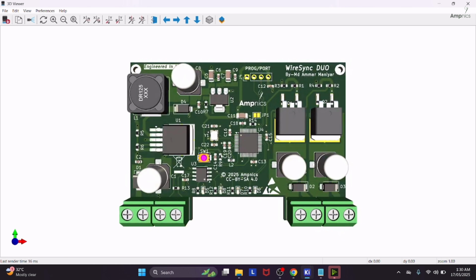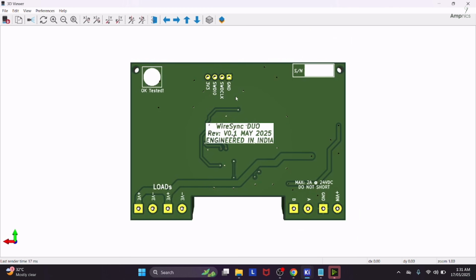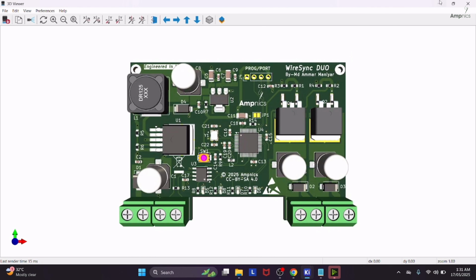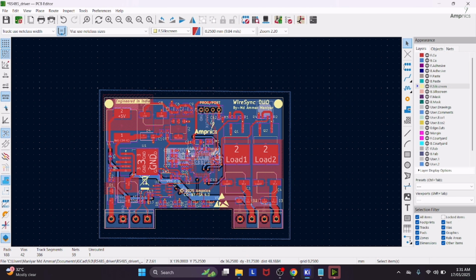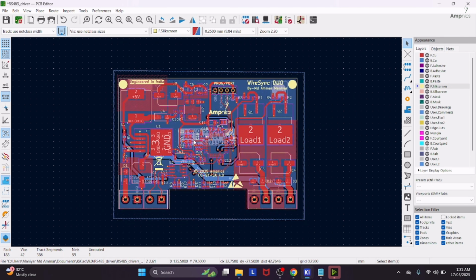Why do we need a PCB like this? When signals start flowing in the traces, they require a return path for that. So if you follow this approach, this will allow you to reduce the EMI and EMC interference. You can avoid it easily. Later on, you may face some noise issues, but if you follow this technique, you will make your life easy.